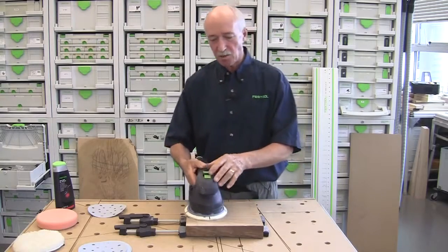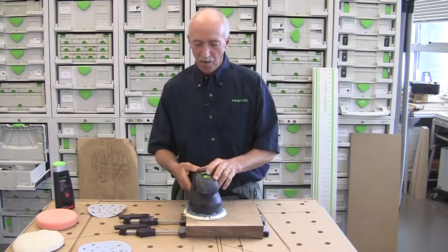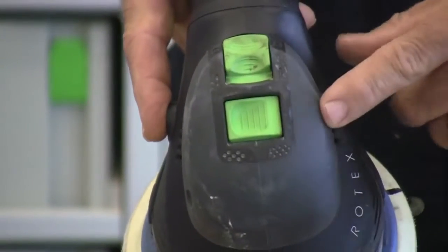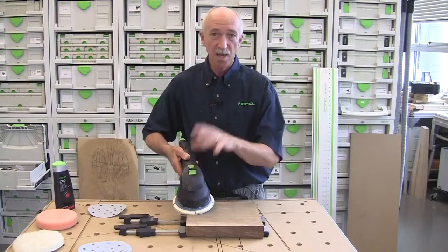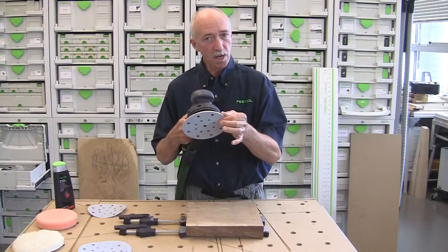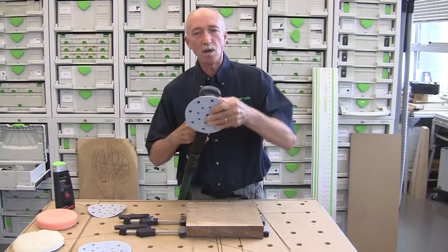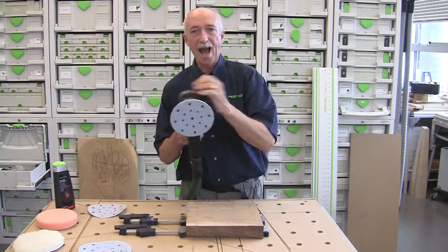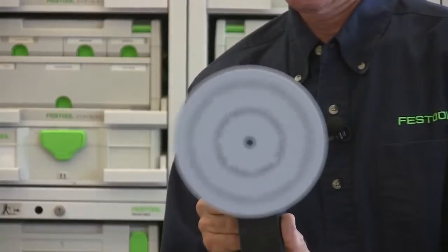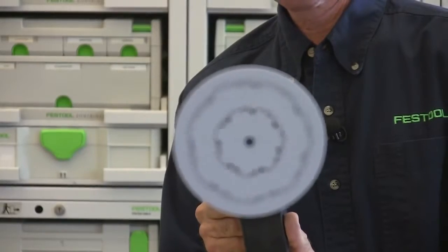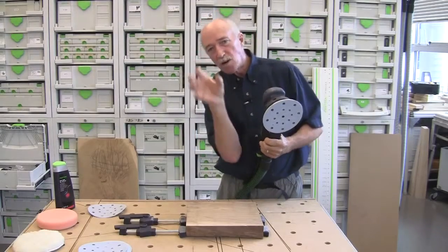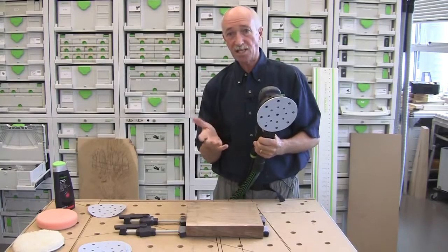This is a Rotex sander, and I want to show the features of how good and fast Rotex sanding works. So we're going to switch over to what's referred to as coarse sanding, but wait till you see the finished product. So you hear the click. Now you're locked in. I am not going to put my thumb on the pad. You can't stop it. So now you have virtually a disc sander with a driven orbital, DA sander.